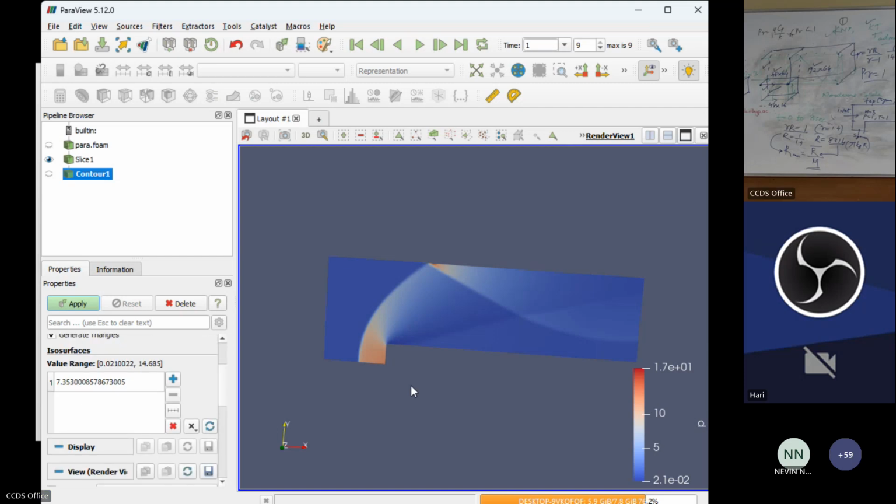What it will do is, this is what we call a filled contour variable. It is filling with colors. We need to make black and white isolines, right? This is density equal to 0.8. So wherever 0.8 is there, it will connect all those points. Then density equal to 1. So again, there would be some line passing near to this. So the shock is basically contained between some range of, let's say, 0.5 to 1.